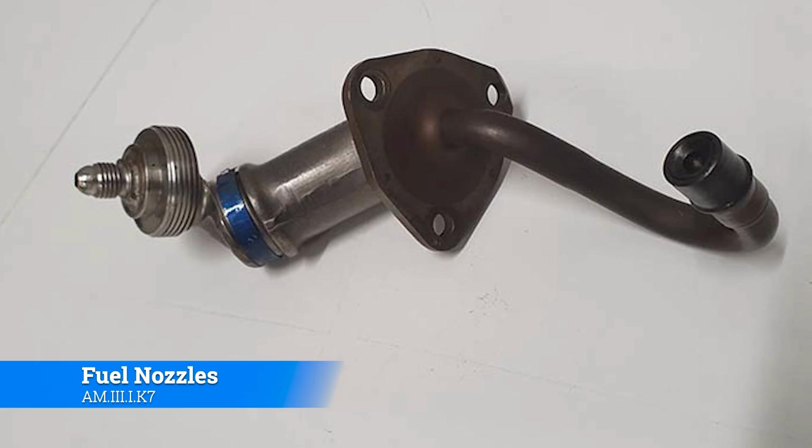Now, the way this works is that the fuel line will go into the left-hand side there. You can kind of see that little boss fitting that tightens up to it, and then this whole fuel nozzle gets put into the combustion chamber. And you notice it bolts onto the combustion chamber, those three flanges right there. But this one is a lot different than the one that we looked at last. Last was literally just like a shower head.